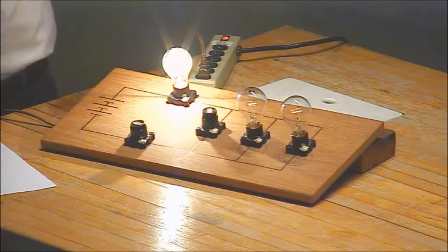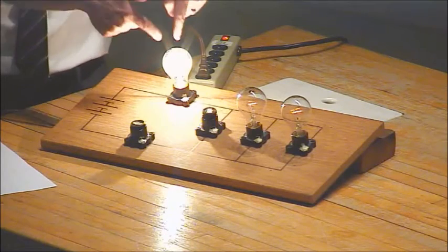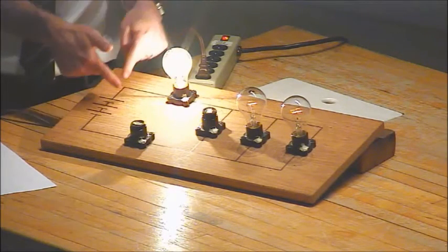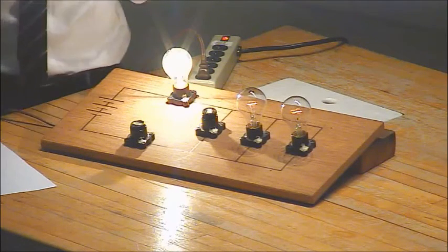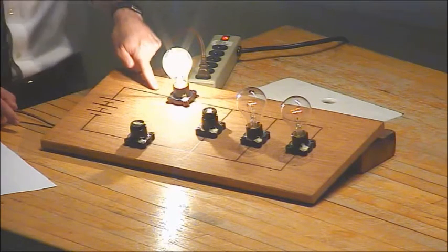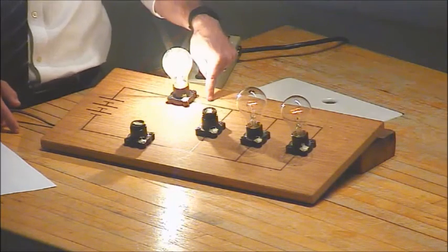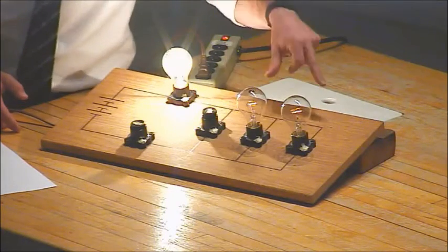So right now I've got these two guys pretty dull, and here's why. I've got a lot of current going through this one. And so most of this 120 is being dropped. I don't know if that's a term I've used yet. When we talk about voltage, we do think of it in terms of altitude. So there's ground, there's high voltage, and anytime you go through a resistive element, you drop voltage. And so there's 120 volts here. Most of it is being dropped across this bulb, and not much is left for these guys. So these guys are both seeing the same voltage, but it's low.